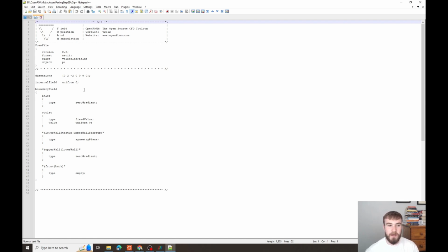You can't have the pressure and velocity both defined at one boundary, say the inlet, because if you apply a pressure and a velocity to an inlet, I believe that will be two Neumann conditions in the same place, or maybe a Dirichlet condition. I can't remember the difference between the two. I believe it's a Dirichlet when you assign a value to a boundary. But anyway, we can't. Basically, the mathematics don't work for assigning both pressure and velocity to that same boundary.